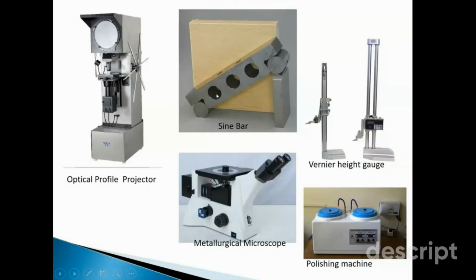The center distance between the center points of these rollers is known to you, and this height is also known to you. All these slip gauges are used in combination to achieve a specific height. With the help of this height and this particular h, if you put all these values in the sine formula, and then take the sine inverse, you can get the angle. This particular angle you can measure.